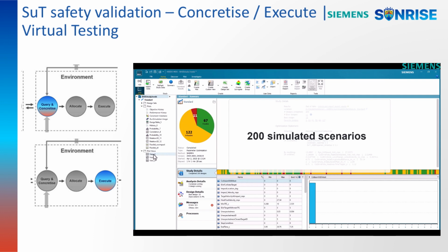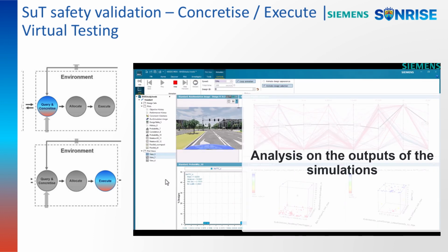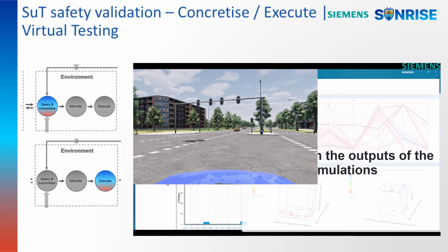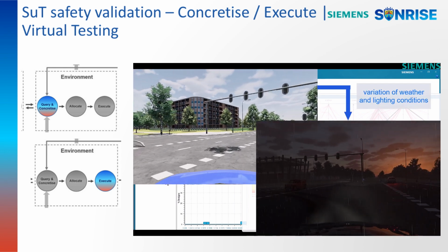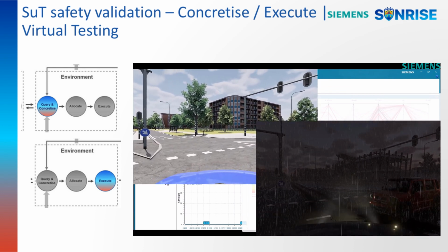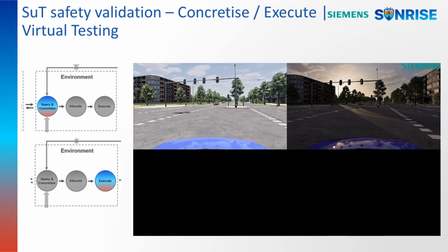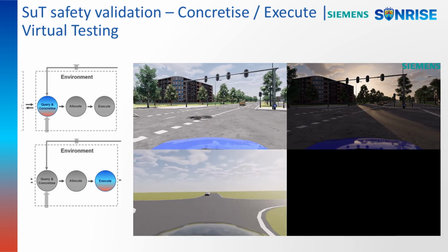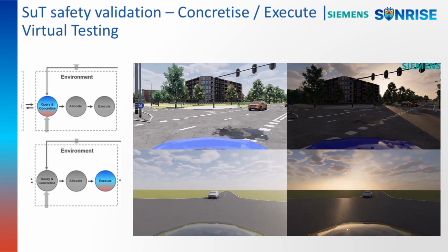This framework begins with a logical scenario and, by varying scenario parameters such as speed and operational design domain parameters like weather and lighting conditions through optimization techniques, it generates critical cases that reveal potential safety issues. This systematic approach ensures that known risks are thoroughly analyzed and mitigated.